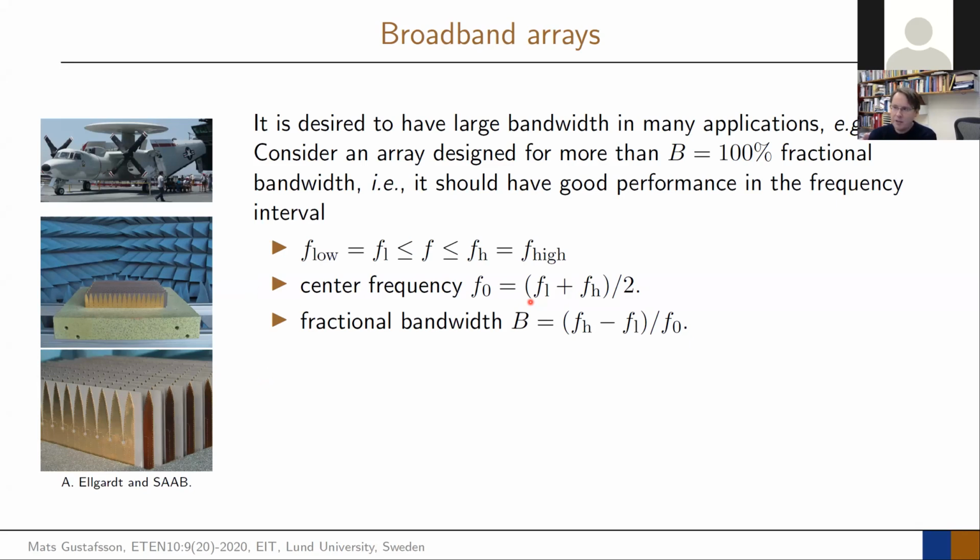And when you design an antenna that is broadband, you have to ask, what is half a wavelength? It's not trivial to say anymore what half a wavelength is, because if you have a huge frequency band, which frequency should you pick, or which wavelength should you pick to call it half a wavelength?